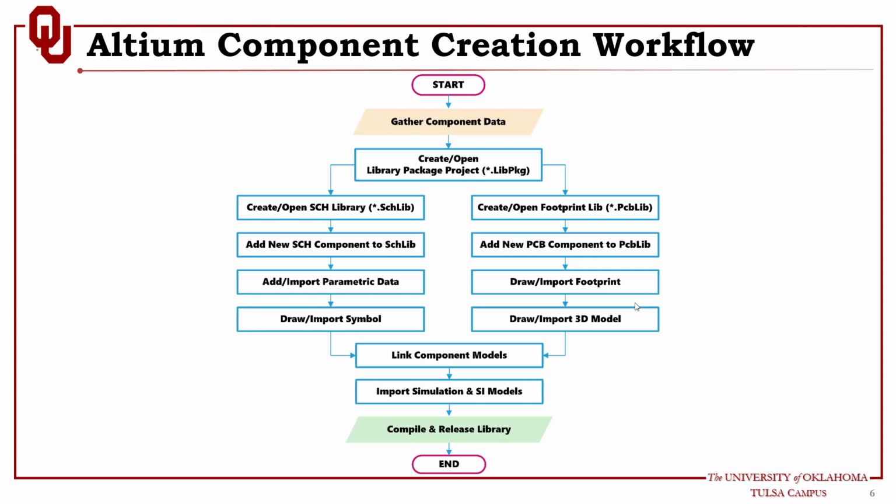Because someone might create a component without enough experience with component libraries, and there is a major problem with this component, and you use it in your design. When you fabricate the design and try to assemble the component, it doesn't fit well, or there is wrong mapping between the schematic pins and the footprint pads, and this will create a problem. You have to redo the work. So you need to verify any external library you are using if it's not coming from Altium directly.